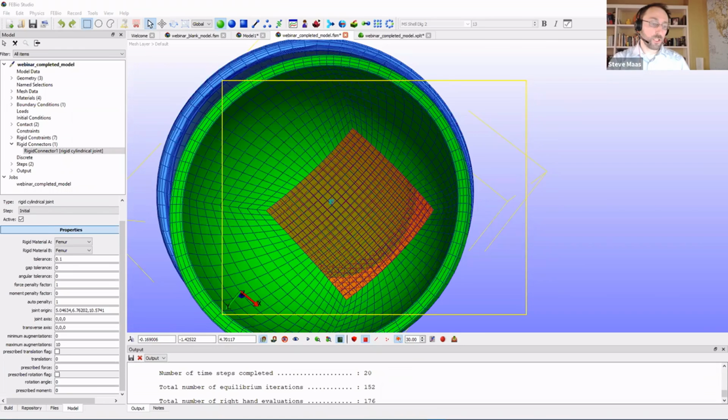Is it possible to change properties of a material in the middle of a simulation? There's not much you can do once the simulation has started. There are some ways to change things like the time step that is being used. If you run FEBio in a shell window or command prompt, you can do Control-C to interrupt the run. So you have a few options to change things, but you cannot change the material parameters in the middle of a simulation.